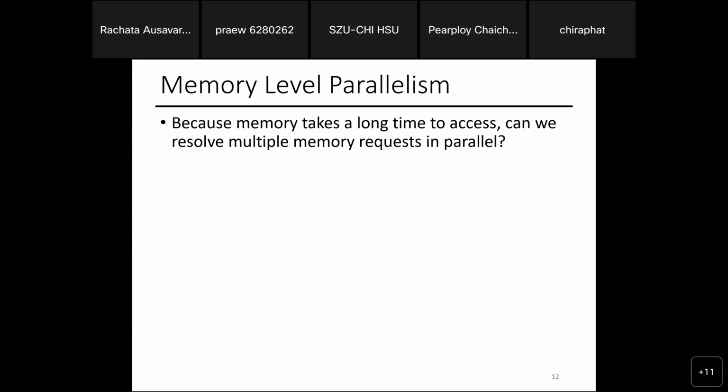So this is a matter of, I don't get the speed, but I get to do a lot of requests at the same time. Right? This is different from a CPU design, which gives you a lot of speed. I can clock really fast. For DRAM, folks, here's your design trade-off. It's super hard to make DRAM fast. I cannot clock them really fast, so my solution is I'll give them a lot of data.